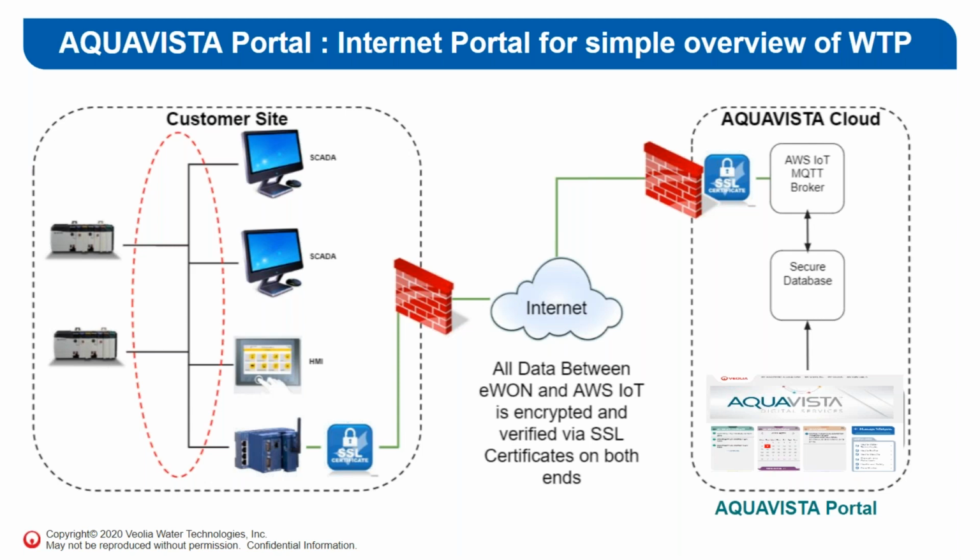So the portal is cloud-based. If you're an existing facility and that's the direction you want to look in, essentially what it consists of is a very simple, inexpensive device we would come out and install in one of the PLC panels at the plant, say your Actiflo PLC control panel. And then we would configure that to pull the key pieces of information, your effluent turbidity, flow information, pH, all of those things that we want to look at and that you need to look at to best optimize and operate your system.